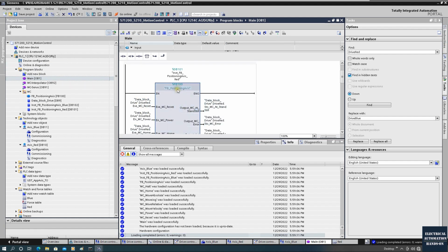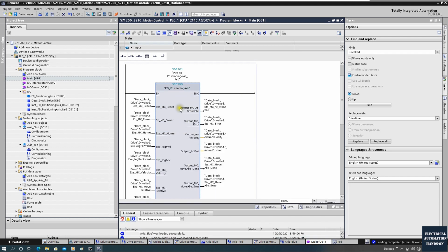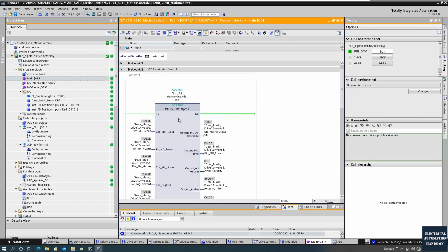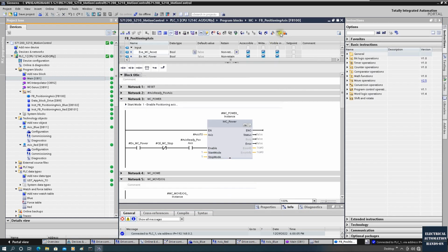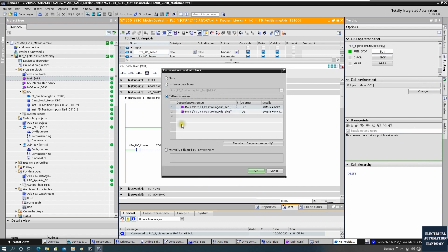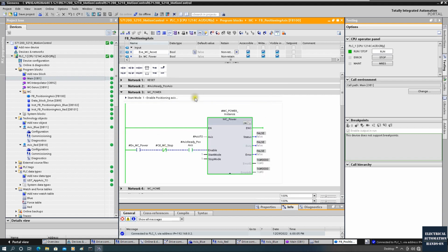So now I'm going to jump into this IB, the instance red, so I can click this online. If I'm going to power up this red first, I can double click this IB, jump into here, and click monitor. In the meantime, we will see this small button. This allows us to switch which motor we are monitoring. So for example, now I'm going to monitor the red. This instance shows this is red, the real status.